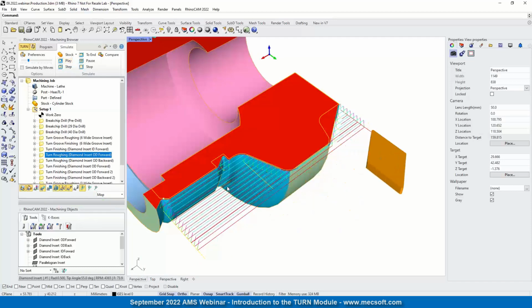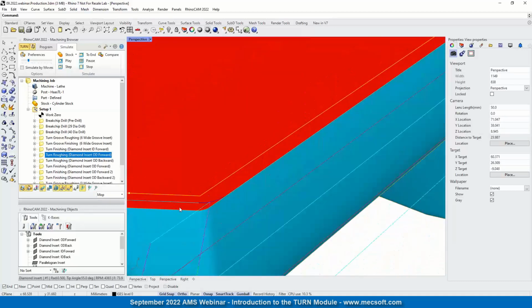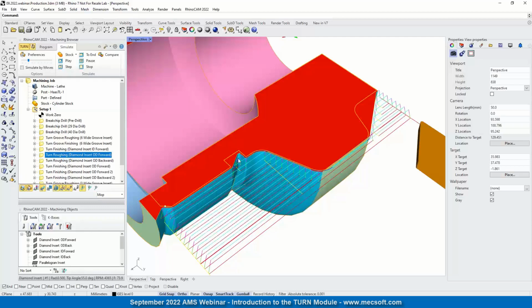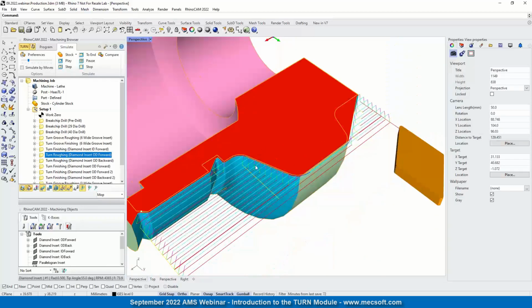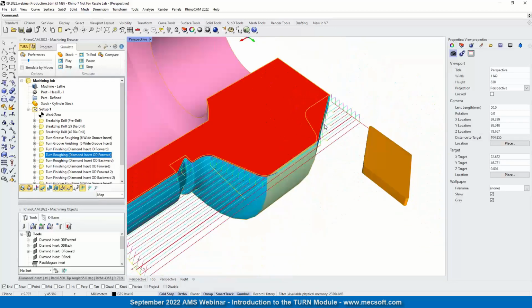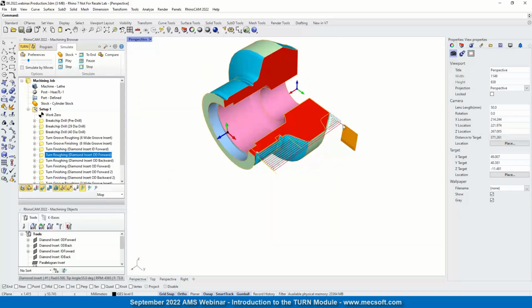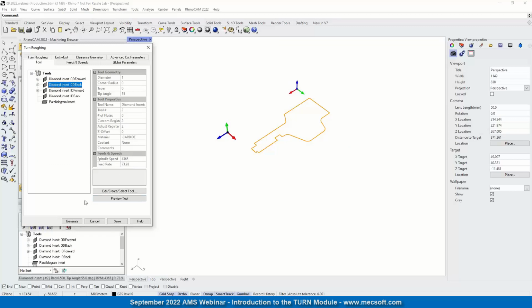So in this particular roughing, we had a finishing pass set. So you'll notice it came back and did a finishing pass, leaving our stock material there. It could not get in all of the groove. That's fine. It leaves our stock material all around, and it will not cut that material out because of the orientation of the tool. That's why we need a second operation with the tool set to OD backward.